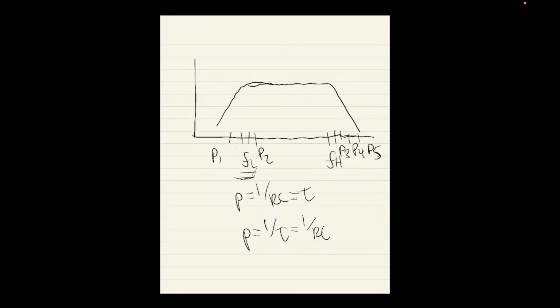So I probably shouldn't have done pole 3. If I made this pole 3 and then got rid of pole 3 here. So you're just adding up these poles right here, and then it would give you maybe some pole there that would be your upper bound. So you know that your gain would cut off at most at that point.